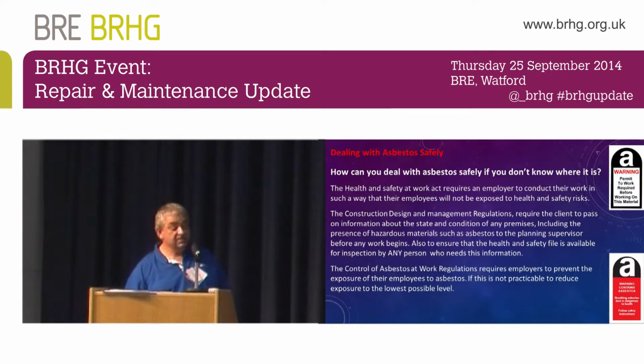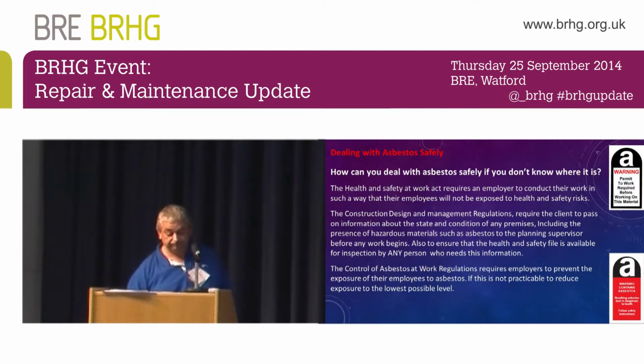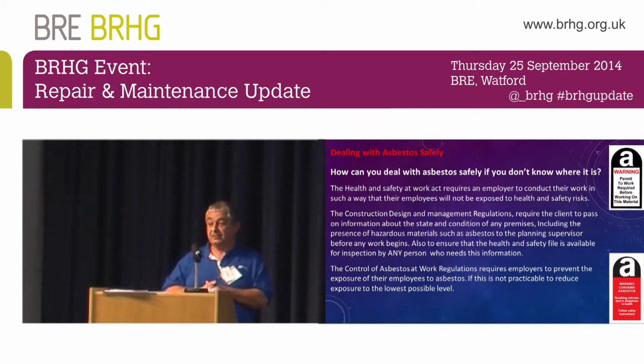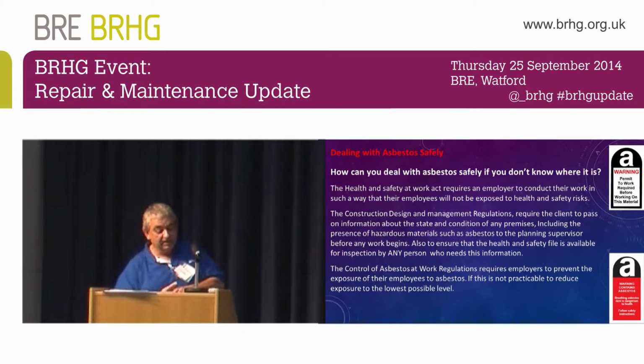How can you deal with asbestos safely if you don't know where it is? As John was saying earlier on, he knows where it all is. He knows where the problems are. The Health and Safety at Work Act requires an employer to conduct their work in such a way that their employees will not be exposed to health and safety risks. That's the first one. The CDM regs require you to have an asbestos register. The client should be able to pass that on before any work begins, and it should be part of the health and safety file.